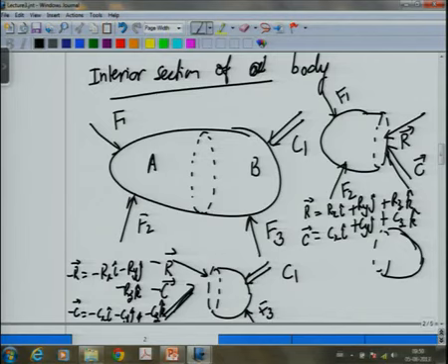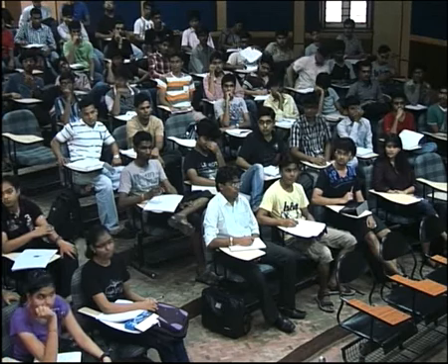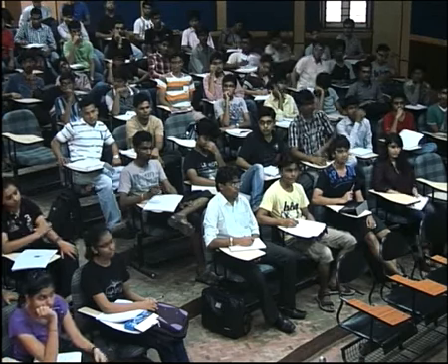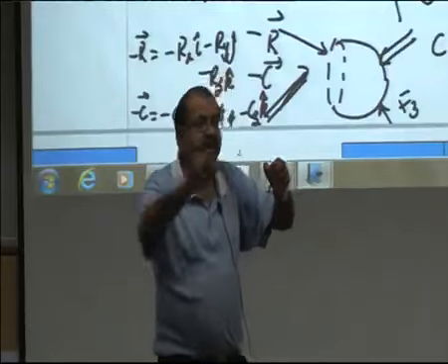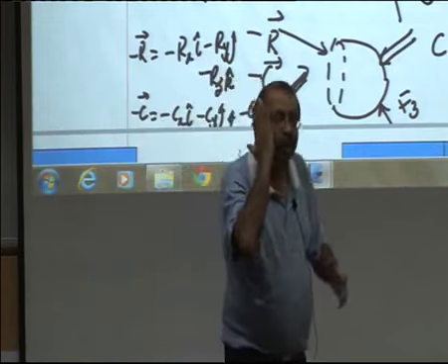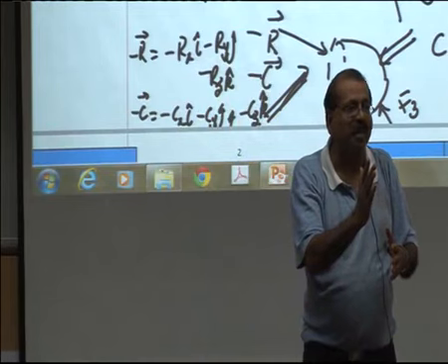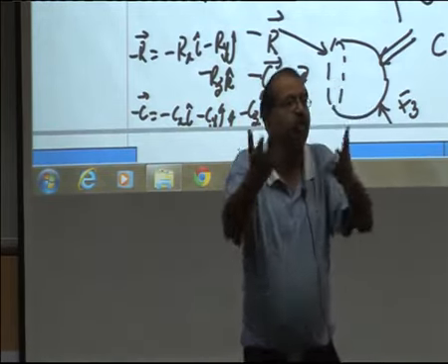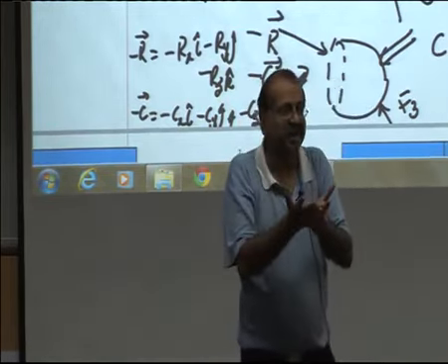Now, why do we need forces on cut sections? Normally we talk of the whole body. Why should I talk of forces in a cut section? Exactly. There is a limit to the mechanical strength. Your section may be very thin at a section. On that cut section you find what the forces and moments are, and that section should be able to bear those forces and moments.